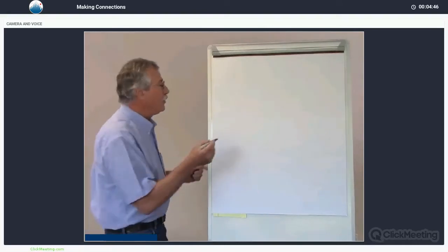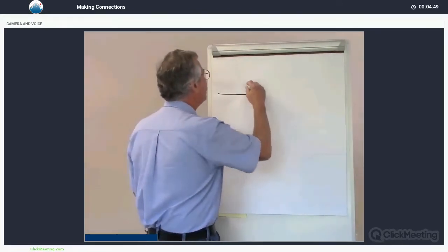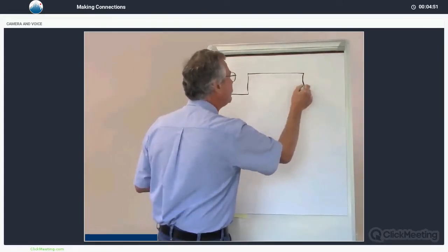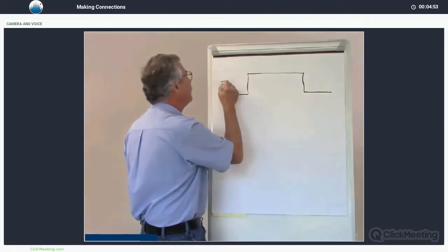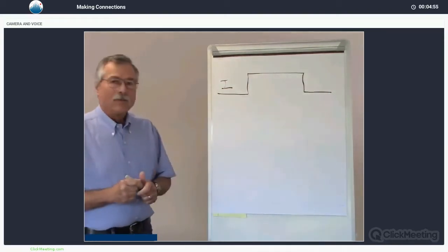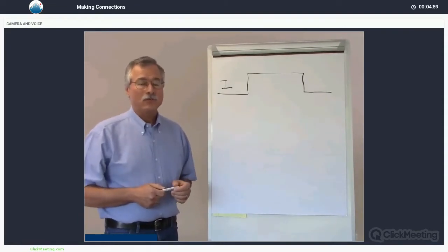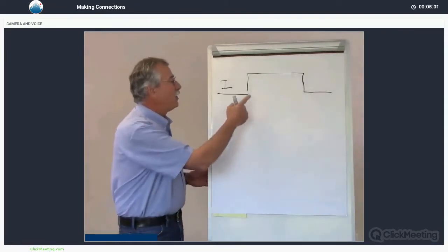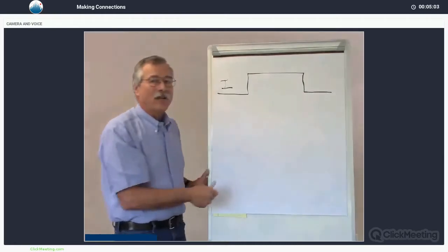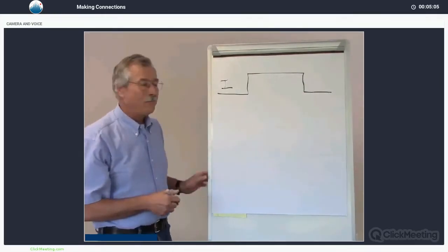This is the pulse that we all want. Laser diodes are current operated devices, and so we use a current source to drive them. What we want is a very fast rise time, a very fast fall time, and a constant current in between.